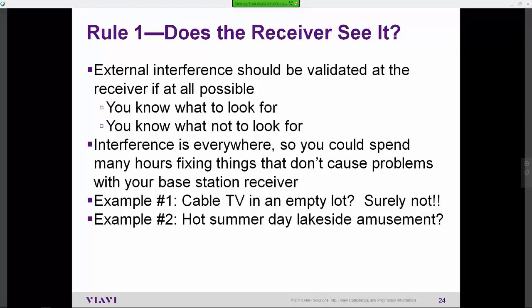But Roy was very quick to point out, and he has lots of experience in doing these path loss calculations, that based on where they were standing and understanding the gain of their antenna, that ultimately the distance from the base station could not have been the source of what was causing that interference to that sector.